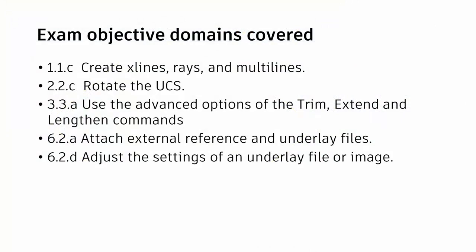In these two videos, part 1 and part 2, we reviewed some techniques to use when creating and modifying multi-lines. We attached an image as an underlay to help place the multi-lines and adjusted the image appearance using the fade control on the ribbon. We also created some multi-line styles using different colors and line types and then added them to the drawing. We used the extend tool and the mledit command to modify the multi-lines. We also modified the multi-line properties by adjusting the line type scale used by the multi-lines. Maybe check out how multi-lines can help you in your AutoCAD workflow as you move forward.